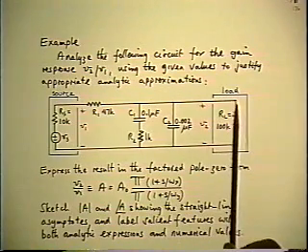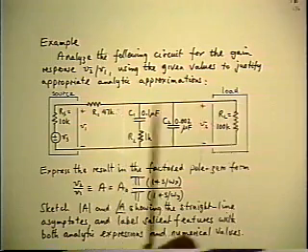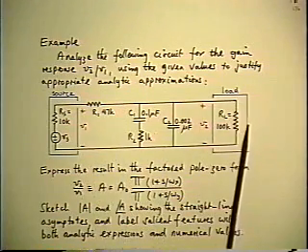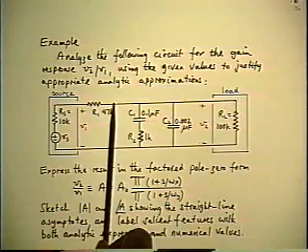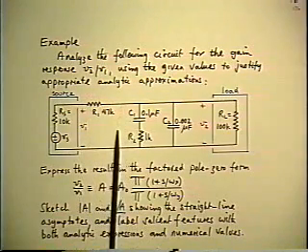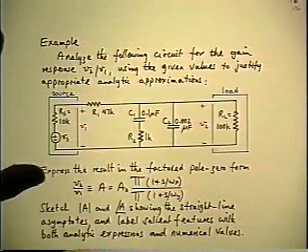This resistor RL could just as well be on the left of the other two branches. It wouldn't change anything, except it's a little more obscure to recognize it when it's out here. But if you simply move the RL to the other side, R1 and RL can immediately be absorbed into a Thevenin equivalent, and you're left with only two parallel branches instead of three.